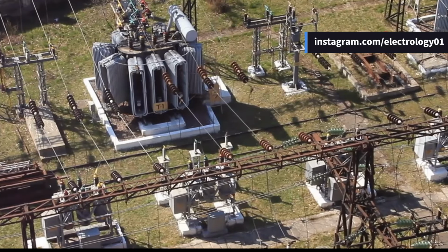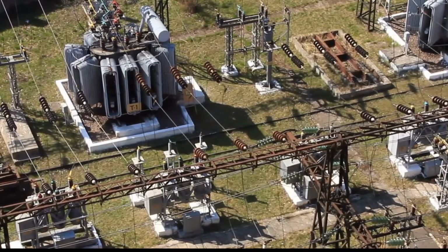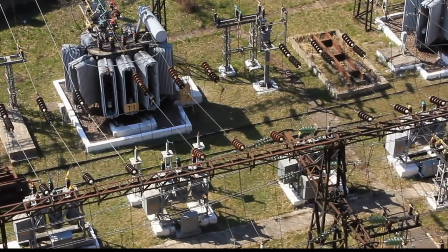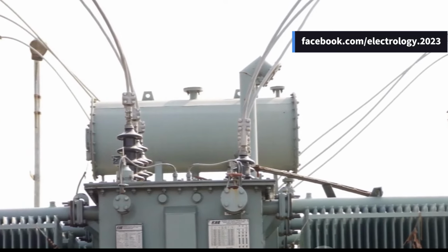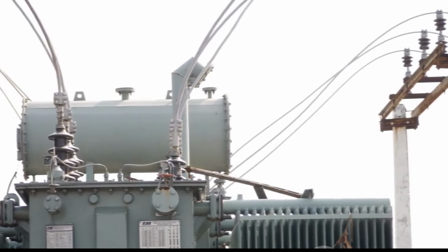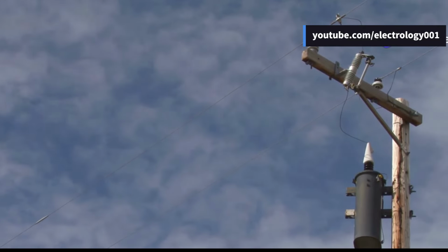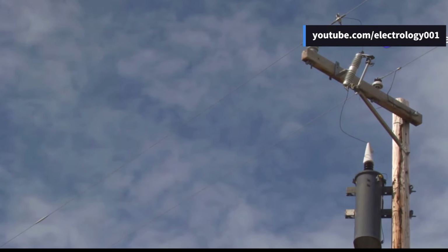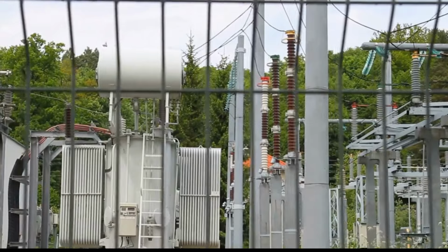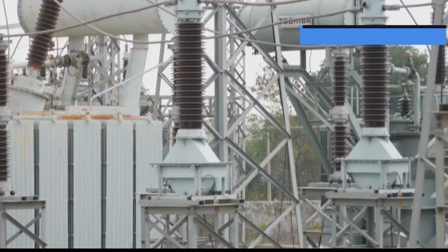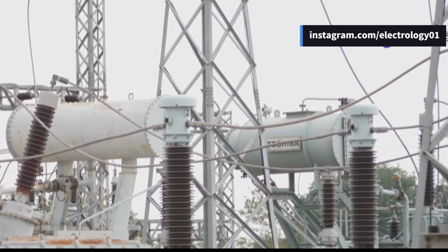Now that we've covered how autotransformers can save on copper, let's dive a bit deeper into the pros and cons of using autotransformers. Like all technologies, they come with their own set of advantages and disadvantages, which we'll discuss in detail. Firstly, the advantages. Autotransformers are smaller in size compared to two-winding transformers of the same power rating, which makes them more compact and easier to install. They also demonstrate higher efficiency, as there are fewer losses due to resistance in the windings. Moreover, autotransformers provide better voltage regulation due to a lower drop in voltage when the load is applied.